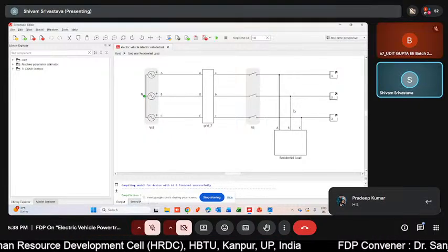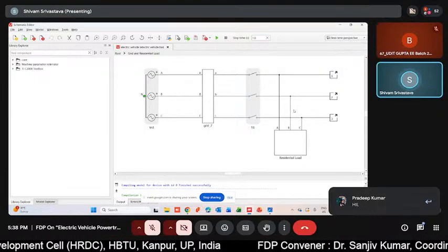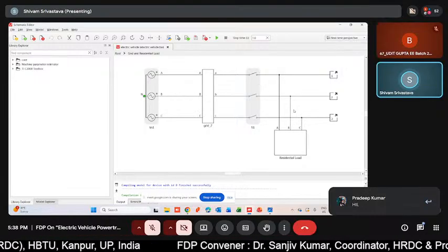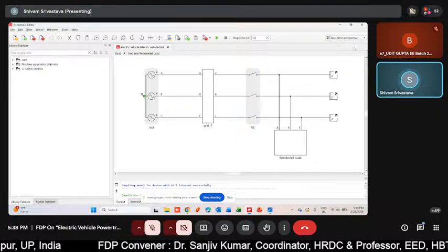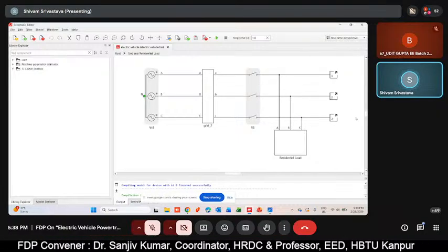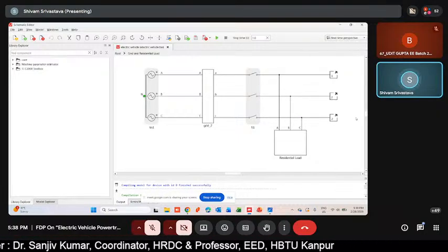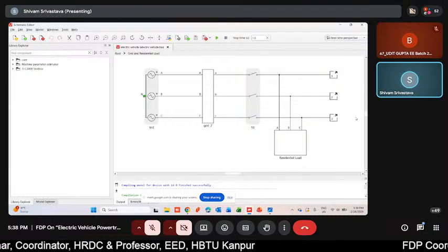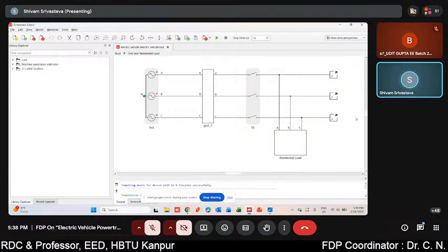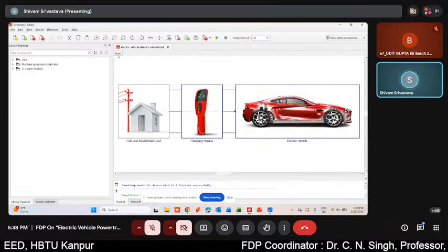That means these black color components are going to run on the FPGA of our HIL device, and the ports by the name of 1, 2, 3 are going to be the electrical ports, not a signal processing port of our device. So this could be done like this.